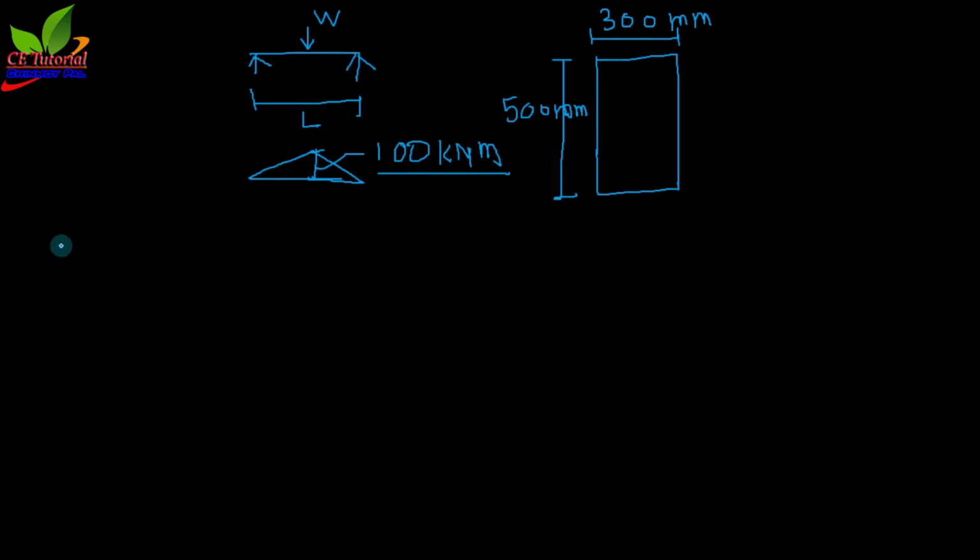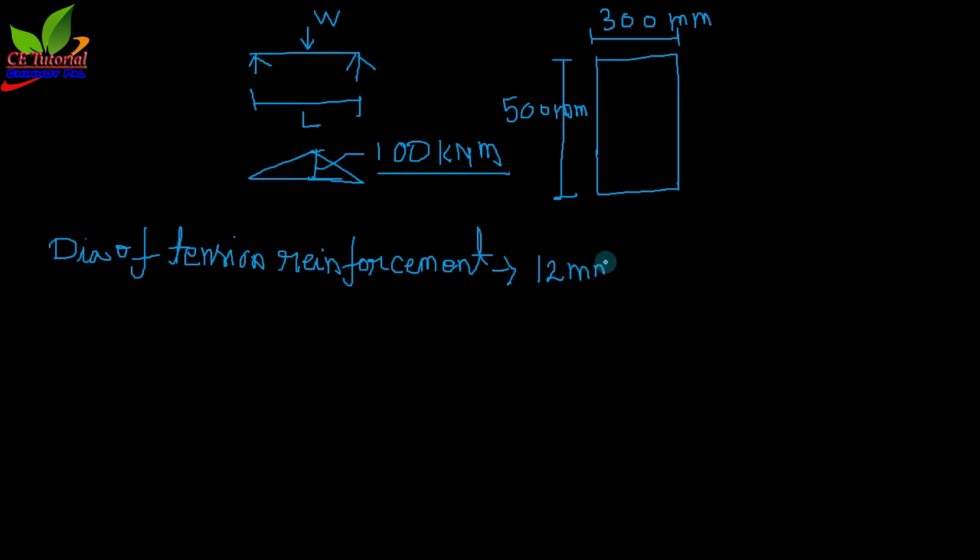Now I have to assume the dia of tension reinforcement, say 12 millimeter, and dia of stirrup say 8 millimeter, and clear cover say 20 millimeter.